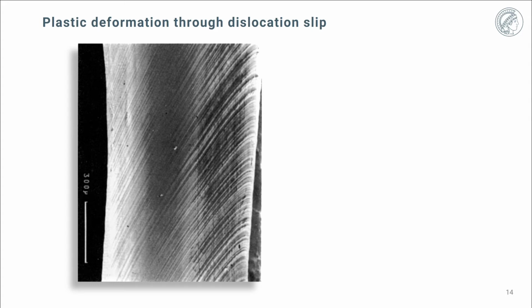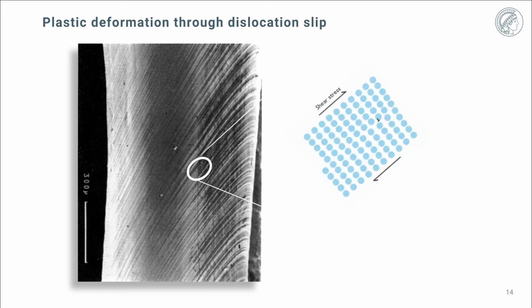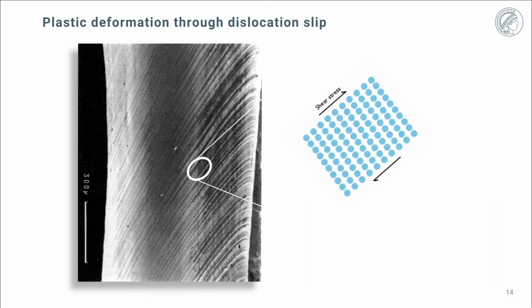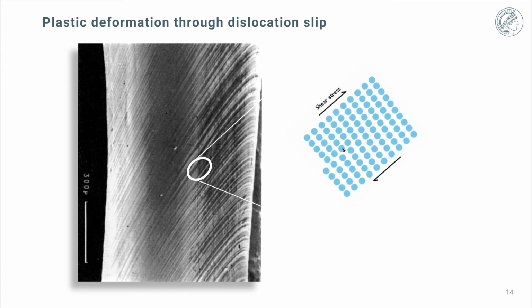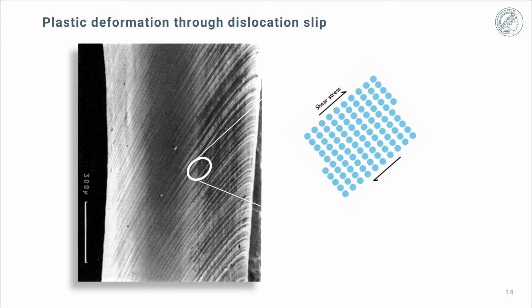So in such metallic materials such as steels and aluminum alloys, the plastic deformation is achieved through the motion of dislocations. Just to remind you of the enormous quantities of these dislocations, when you have a cubic meter of crystalline metallic material, then you have up to 1 light year of dislocation length in such a cubic box. That means about 10^16 meters per cubic meter.